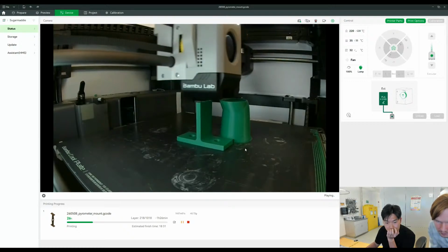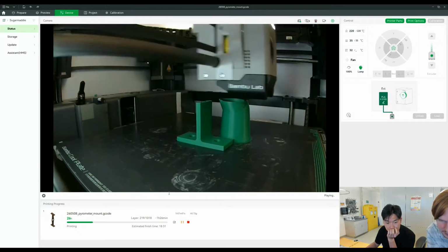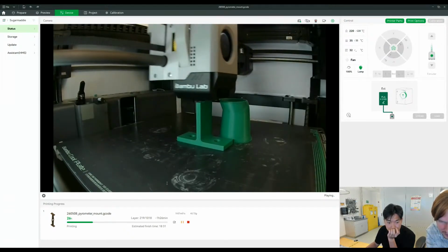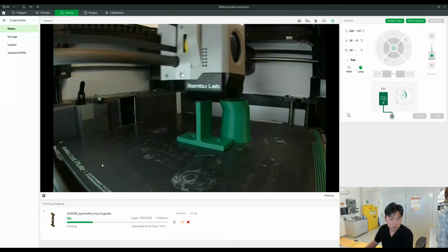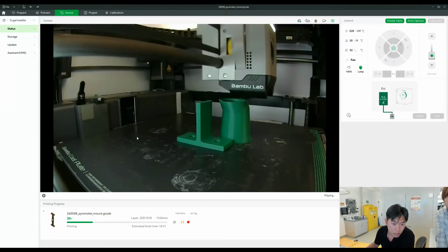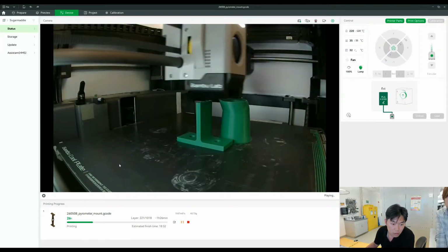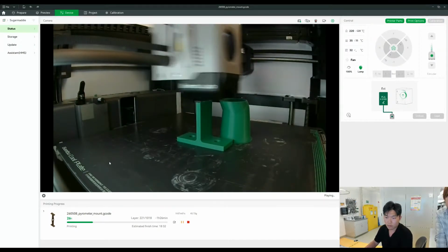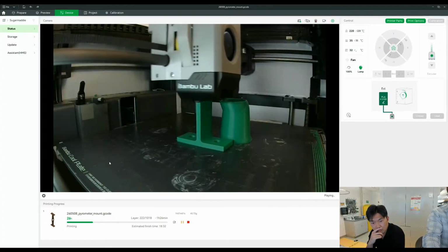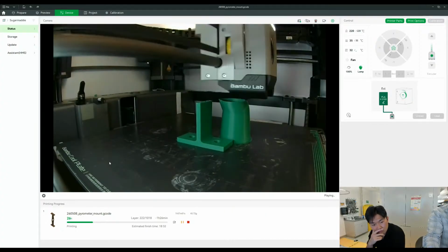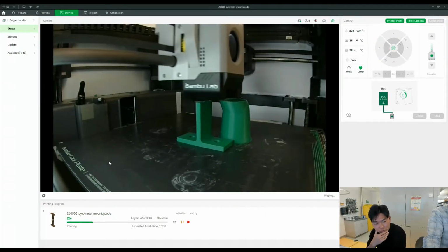Okay. And see, as you increase the voltage, it increases the true RMS. So that's basically varying the power as a percentage of line voltage. At 5 volts, you have 100%. At 0, you're at 0%. It's not exactly linear near the ends, but in the middle it's pretty linear.